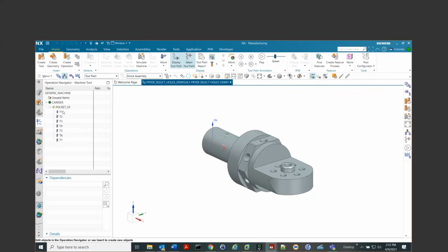To save time, I've already added the tools that we're going to be using in this presentation. The geometry view, where we store the different geometry groups that we create or part boundaries or anything like that. And then we have our methods group. Based on the method, the tool, and the geometry, we can define speeds and feeds automatically. Switch back to here for now.